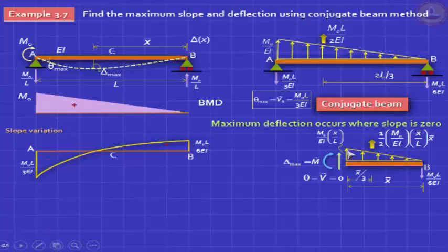Remember our discussion in the last lecture, it has units of kilonewton per meter. Look at the variation. When X bar is 0, it's 0, and it's linearly varying to this quantity. So you have to first derive this from this by similar triangles. Then you get this area, which is this into half, and then equate this to this.